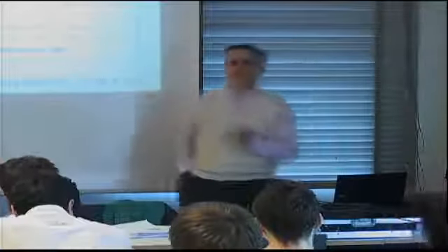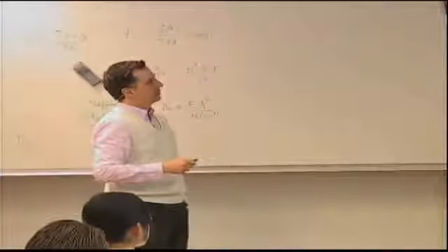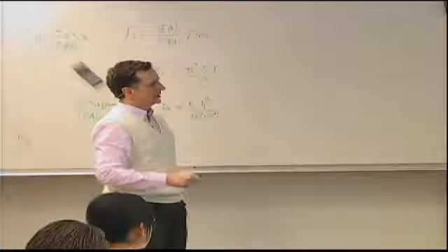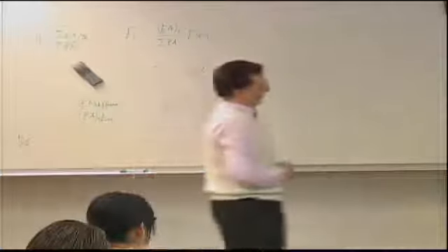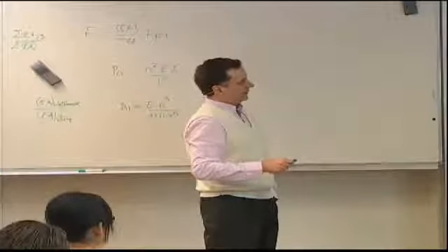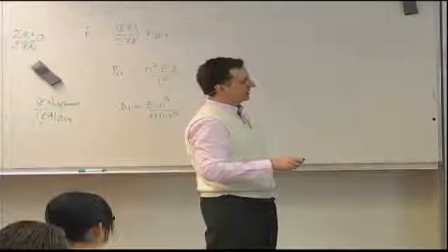Let's take the 3-ply fabric flange, which was the rightmost column in the previous chart, and plot this maximum fastener spacing, S max, as a function of B over T. So what we find is there are 2 curves, one for the protruding head because of the factor of 3, and the other for the countersunk fasteners.